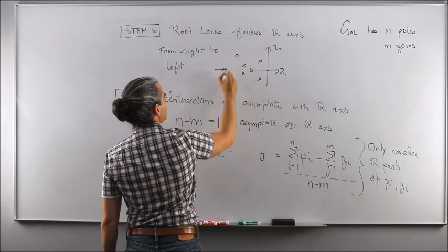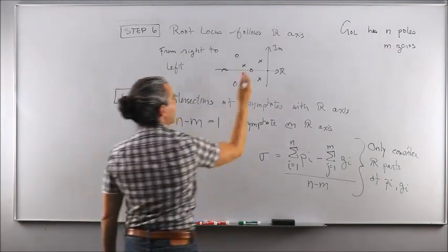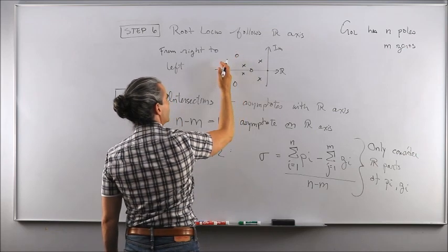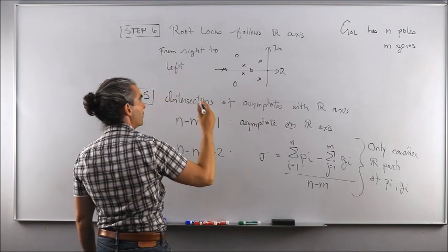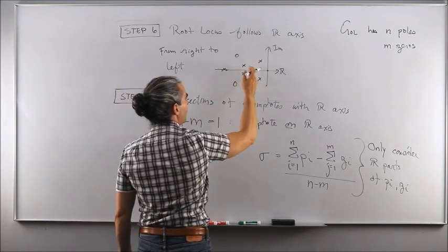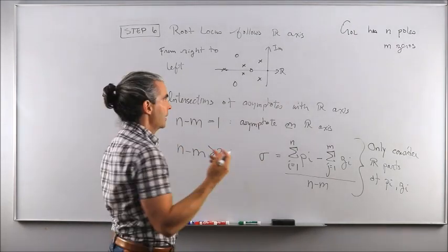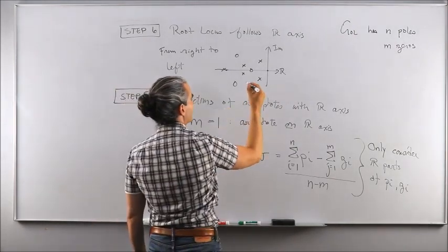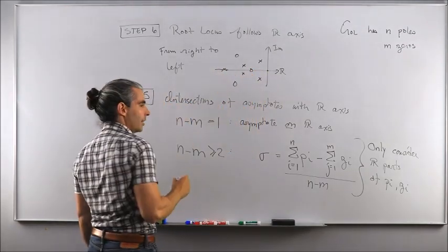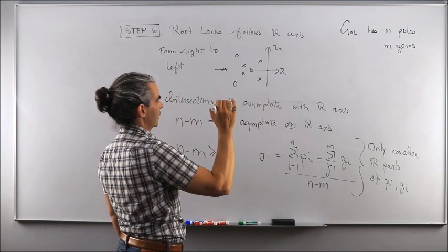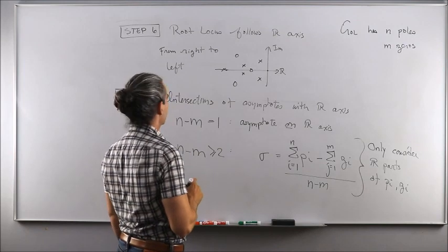If that is the open loop zeros and poles you have for the open loop transfer function, you start here and you count all the zeros and poles that you encounter as you move further to the left. And whenever the summation of any poles and zeros you encounter gives you an odd number, that means that the root locus will lie on the real axis at that point. If you get an even number, you stop drawing root locus on the real axis, okay?